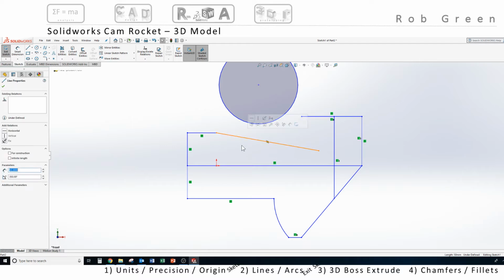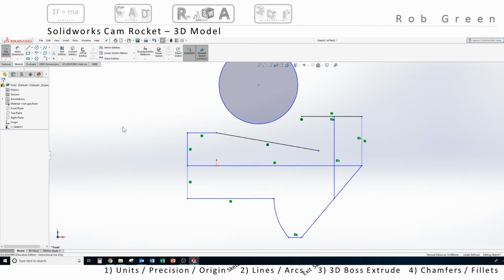Remember, I'm going to select this line, hover over the endpoint that the circle is supposed to pass through. I'm going to press Control and hold it, and then click on the orange endpoint. I can see here in the properties that I have a line and a point selected. I'm going to tell Solidworks by clicking on this fix relation that I want to fix both of those pieces of geometry in space. And if you do that, look on your screen and you will see that you have two pretty little boat anchors show up on your screen, clearly saying that we're going to fix those into position.